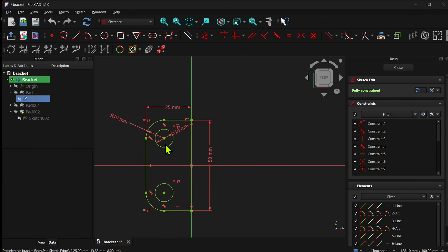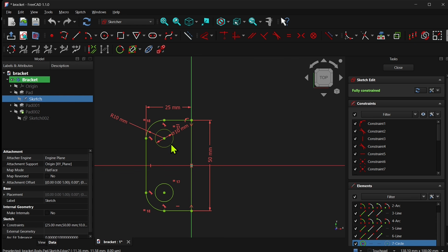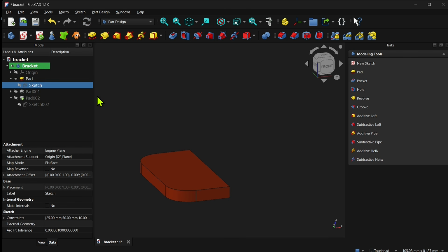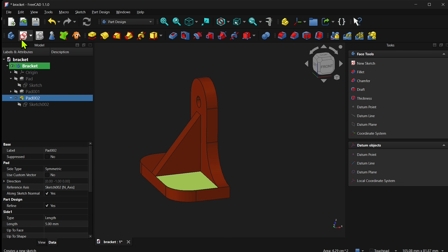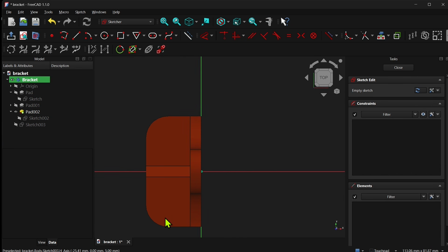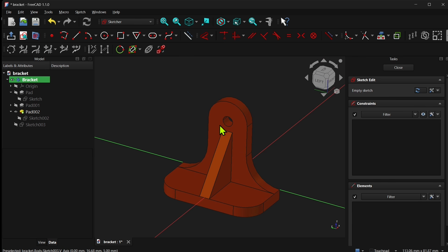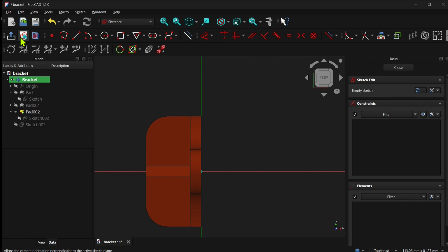In here we can see the 10mm holes. Select one and then select the other. This gets added to the selection, and we'll hit the delete key, removing those holes. We can now close the sketch and show the last operation. Those holes have been removed, and now we select the top of the face and create a new sketch. Now this sketch will be on the same plane as this face, and if we add some angle, we can see where that's intersecting. Select the view sketch to reorientate the view, and I'm just going to select the toggle section view to cut through that.